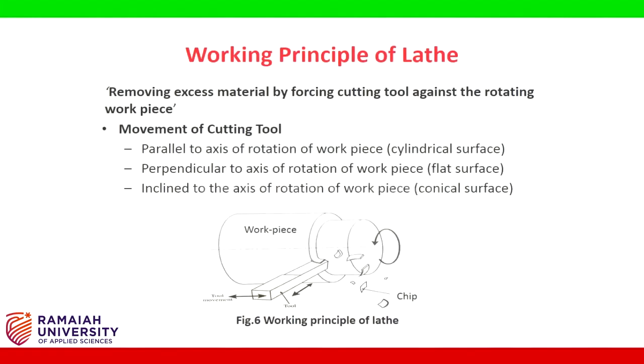Working principle of lathe: removing excess material by forcing cutting tool against the rotating workpiece. Movement of cutting tool: parallel to axis of rotation of workpiece, cylindrical surface; perpendicular to axis of rotation of workpiece, flat surface; inclined to the axis of rotation of workpiece, conical surface.